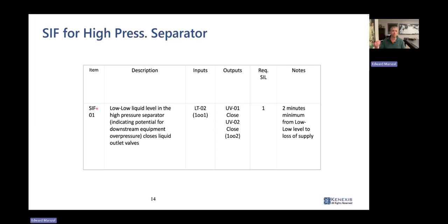Or the thing that is more commonly done is you will use UZC instead of LZC because the letter U means multivariable. And for most safety instrumented functions, there are many variables that will trigger the action and many final elements. Going forward, you will see us, and hopefully everyone, when tagging safety instrumented functions, call it a UZC instead of a SIF or an I for interlock or whatever else.